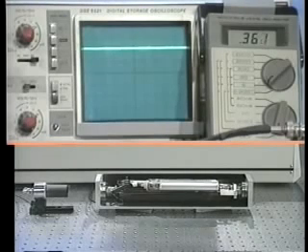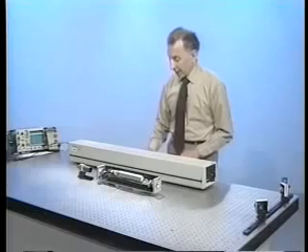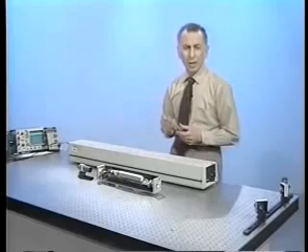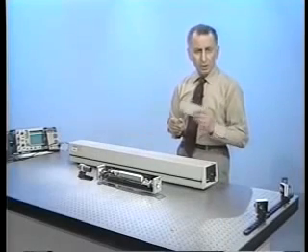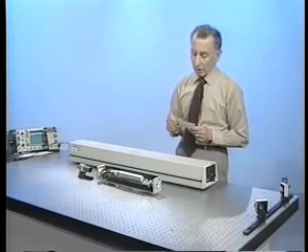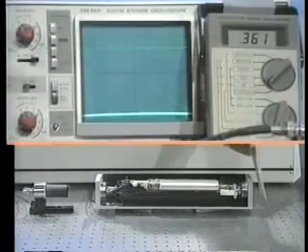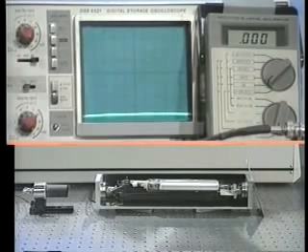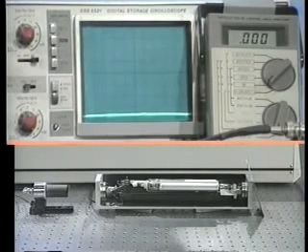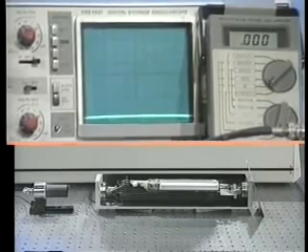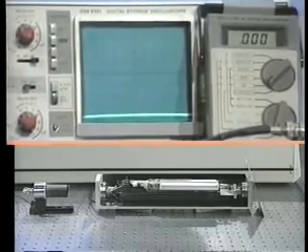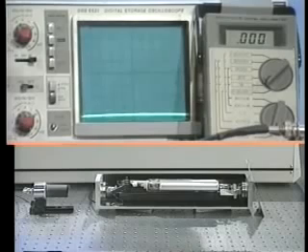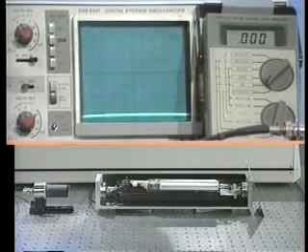Now you may wonder that maybe what we're getting, when I turn on the amplifier, is light from the amplifier that hits the detector. It's not really amplification. So to prove this, what I'm going to do is block the beam of light going into the amplifier so that there's no light going on the detector. We're back to our 0 on the meter. And now I'm going to turn on the amplifier just by itself, just to see if any light from the amplifier is falling on the detector. So here we go. Watch the meter and the scope.